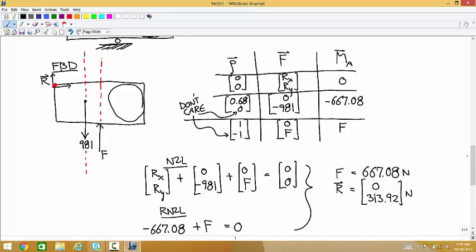And you can see that in doing this calculation of the moment produced by the weight force, if the x location of that centroid changed, that cross product would change, the moment would change, and so these values depend on the correct location for that weight force. Okay. If you move that weight somewhere else horizontally, you get different answers. Wrong answers.